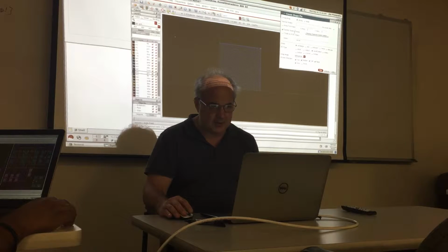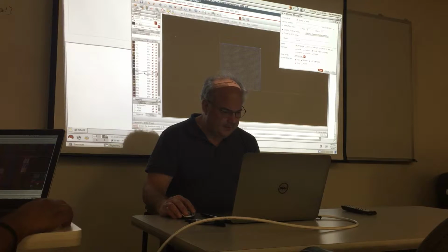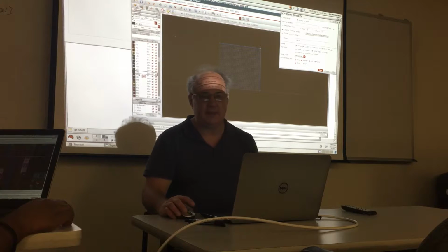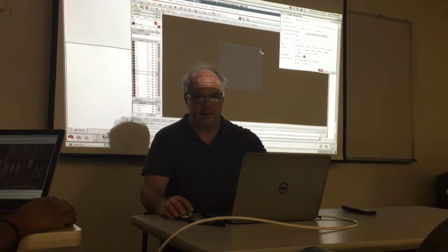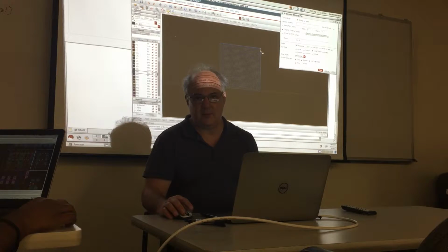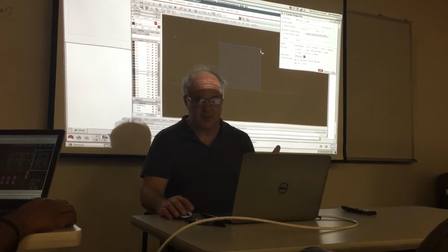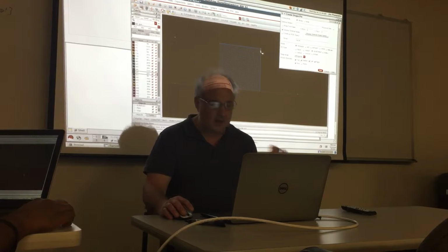Okay, so you bring up the menu, and then you want to make sure pin is selected as the drawing layer, right? Because when you actually click and create that X, it's going to draw in that layer, which is this layer purpose pair they call it. It's a metal one pin.